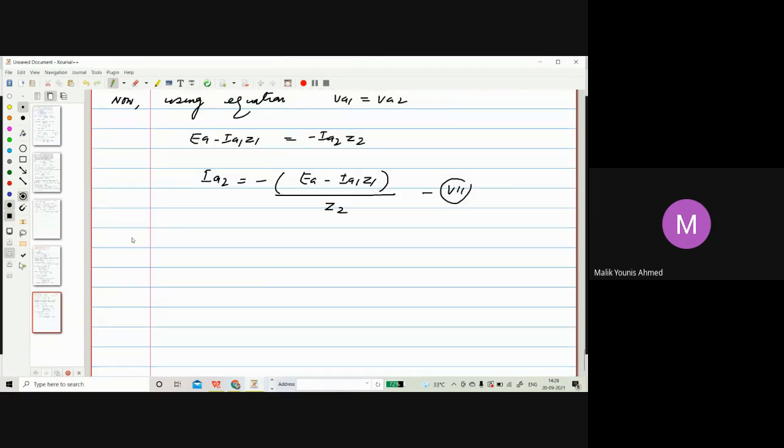We know IA is equal to IA0 plus IA1 plus IA2. And we know IA is 0 in this case, post-fault conditions, since the fault occurs at phase B and C, not phase A. So this is 0. Then, IA0 value we have got just now.